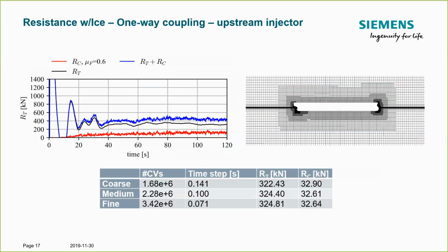Now, first thing is let's do the due diligence and get a feeling for what the discretization sensitivity is for the grid that we use. The grid that's being used doesn't differ too much from what you would be using for an open water condition, except that we have these ice sheets to the right and to the left, and have to assign appropriate boundary conditions to their walls.